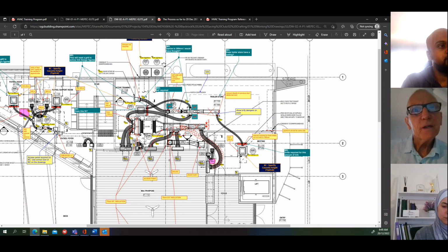But the point is that 600 by 450 is what the workshop needs to know to manufacture that duct, because that is the sheet metal size, and then the insulation. So they make the ductwork first, and then they apply the insulation after the duct is made.